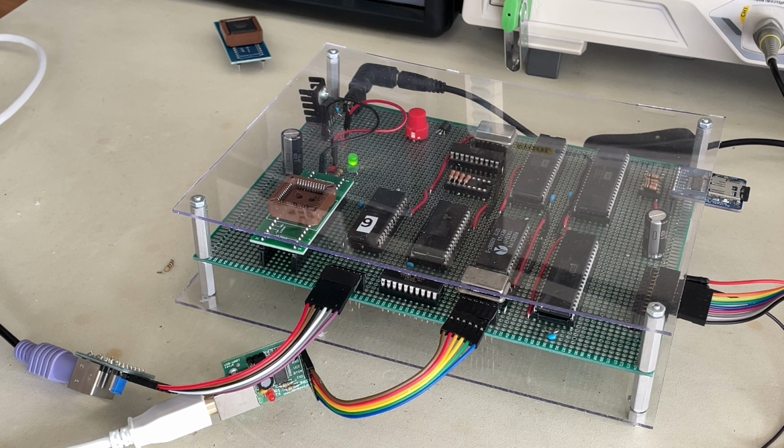So SPI is the serial peripheral interface, a serial protocol for accessing peripheral devices. It's sort of a little like USB in some ways, although it's not nearly as fast or as complicated as USB. It was originally developed by Motorola, and it's used now by a bunch of microcontroller systems, and so it's especially used for microcontrollers talking to sensors. But there's a huge range of SPI devices available: network interfaces, all sorts of sensors, storage, and other I/O devices. So it's a pretty versatile way to get a 6502 to talk to the world.